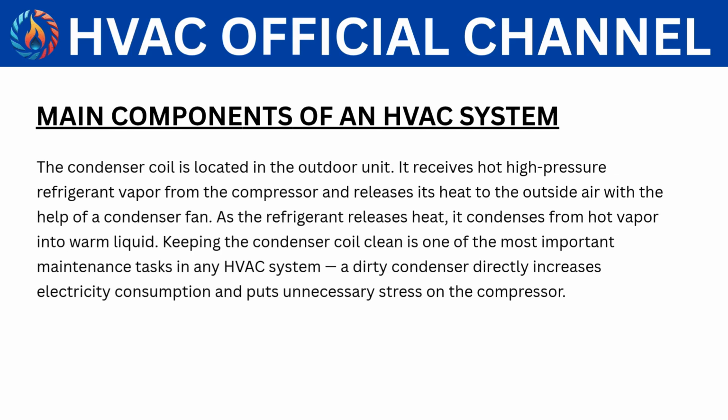The condenser coil is located in the outdoor unit. It receives hot, high-pressure refrigerant vapor from the compressor and releases its heat to the outside air with the help of a condenser fan. As the refrigerant releases heat, it condenses from hot vapor into warm liquid. Keeping the condenser coil clean is one of the most important maintenance tasks in any HVAC system. A dirty condenser directly increases electricity consumption and puts unnecessary stress on the compressor.